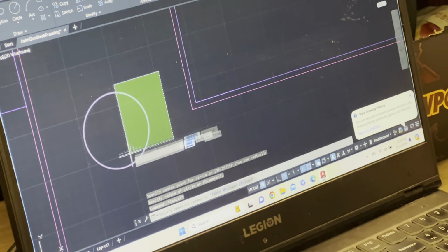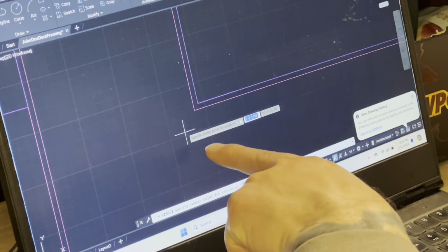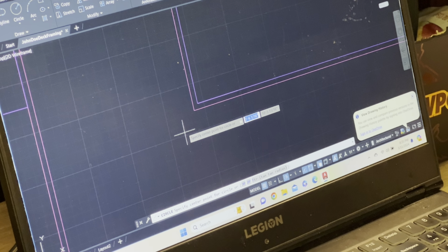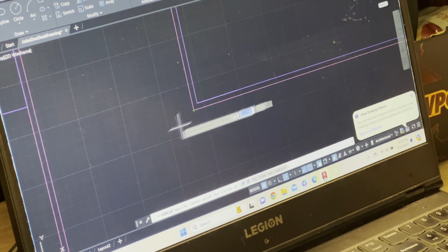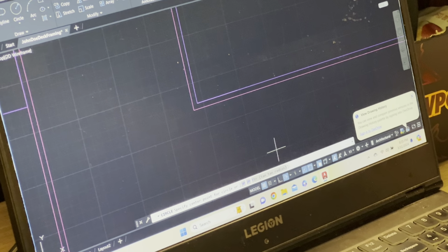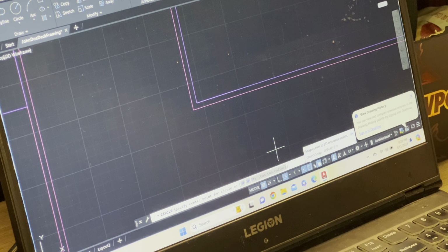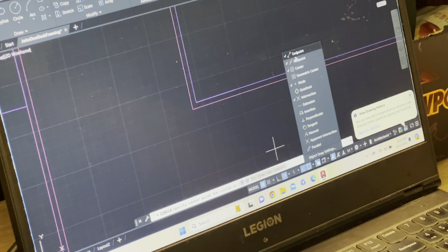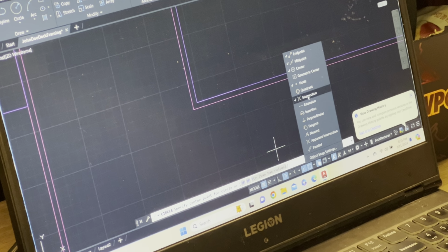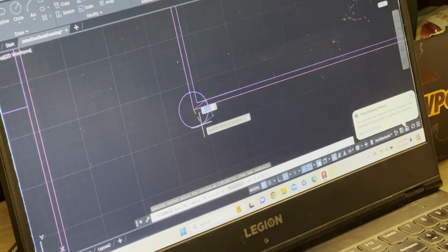Pretty basic, right? If you watch your cursor, when you click on something, so right here, let's say, it'll say specify center point for circle, or, and it'll give you options. I could press down, and it'll give me more options. You see how my cursor snaps to points. That's because that's an intersection and it's an end point. If I go in here and I change on this little symbol here, hover over it, it'll say snap cursor to 2D reference points. If I click the little down arrow, that's where the options pop up. And I could set anything. Right now it's set to where I can click endpoints, intersections.